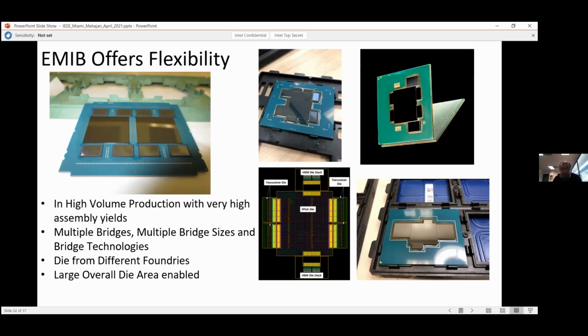So the question I have is, when you connect these chiplets to each other, you're making use of, let's say, AIB, right? So what is the additional real estate taken up by this AIB? If you compare the monolithic approach with this heterogeneous approach, taking into account the area taken up by that AIB, what is the difference? How much extra area is required? It's about 1 to 2% more, depending on the link. Yeah, because these are typically almost bump limited. And when we get to low bump pitch, they're roughly bump pitch limited. So at 55 micron pitch, it's a very, very low overhead. It is an overhead, but a very minimized one. And that number is rough. I can get you the exact numbers, but roughly that much.